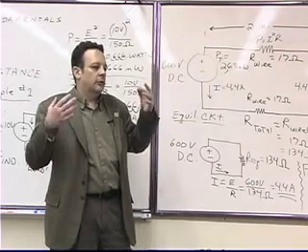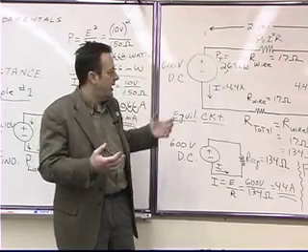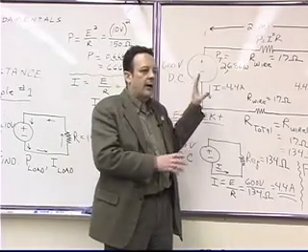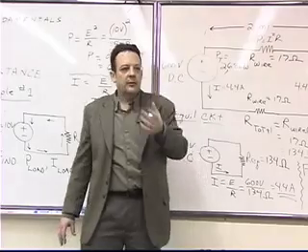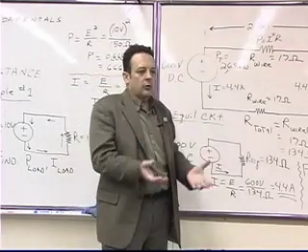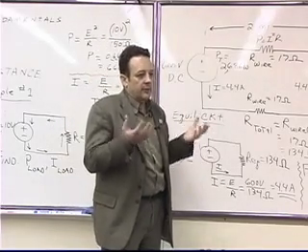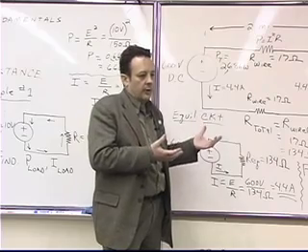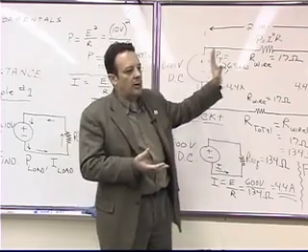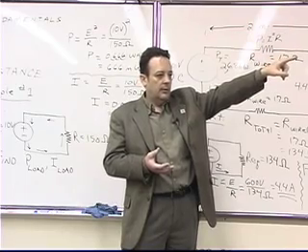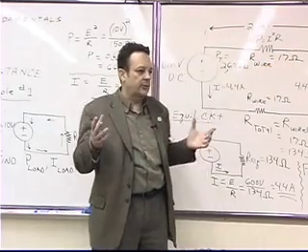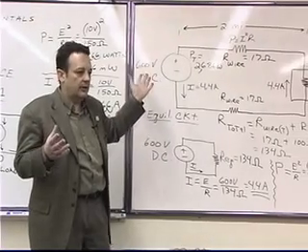Well, if you're smart about it, you're going to sit down and you're going to analyze how efficient that system would be. And then you're going to come back to the owner and say, agreed, you have a lot of excess power in your solar panels. But to use it to drive a water pump that's 2 miles down your property is going to be a highly inefficient utilization of that energy.